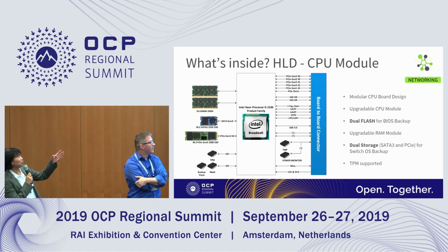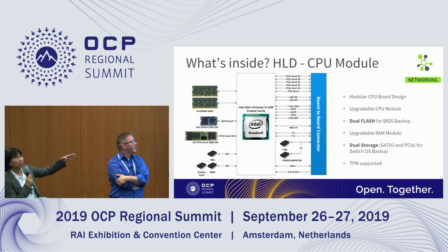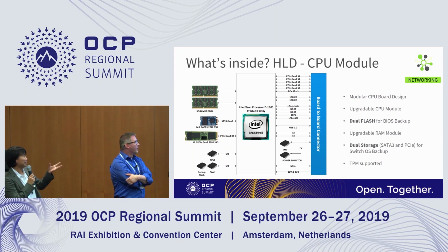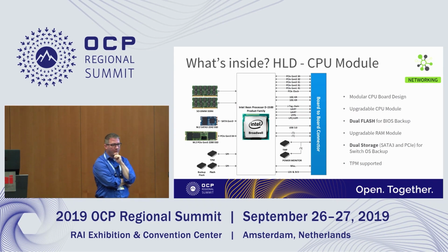Here it is the D1500, but we can change it to the D1600, then we can connect 4 10G. So we reserve that. The reason is the D1500 only supports 2 10G, while the D1600 supports 4 10Gs. If we would go for the D1600, the driver would be to have IPsec encryption, so you need additional bandwidth. But from the ASIC, we just take one of these 25G SerDes quads, and all of those 4 links are provided on the board. The PCI Express will be just a pure control plane for the ASIC. No packets.